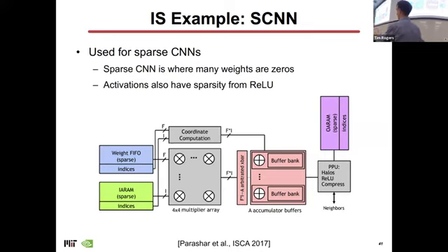And so there's sparsity in the weights, there's also sparsity in the activations, because every time you multiply by a zero weight, you're going to get another zero. And then the ReLU also makes it additionally sparse. So sparsity is all over the place. How you exploit sparsity is one of the fields that is actively being looked at in both commercial systems and academically. And so this paper was a relatively simple way, I guess you could think of it, to accelerate these sparse matrices where you've got these zeros all over the place. And they did it essentially with indices.